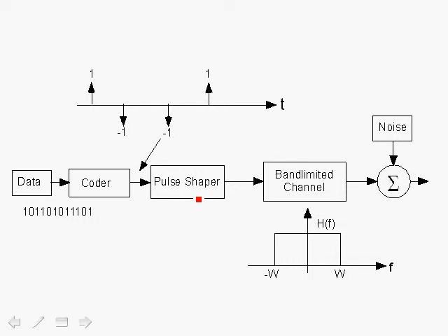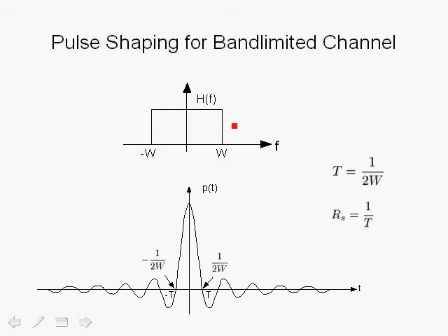Since the pulse shaper is a linear system and we have a chain of impulses, each representing a symbol, which have been mapped from the binary ones and zeros, the output of the pulse shaper is a superposition of the impulse responses of the incoming signal. Each impulse response, by the definition of the pulse shaper, will be band-limited to less than W hertz, and therefore we meet our requirements for the baseband digital communication link.